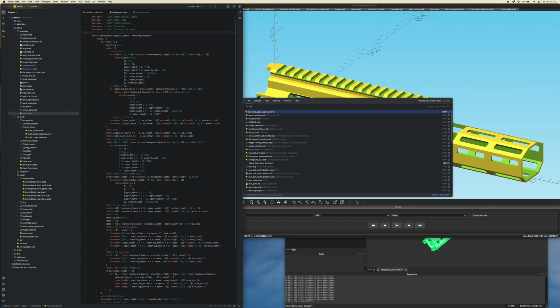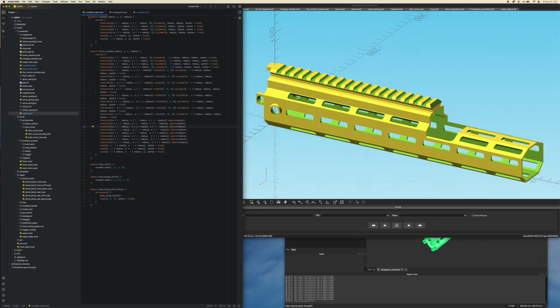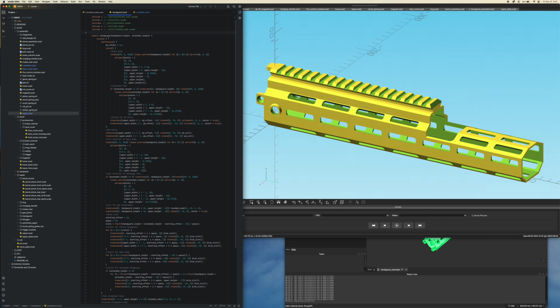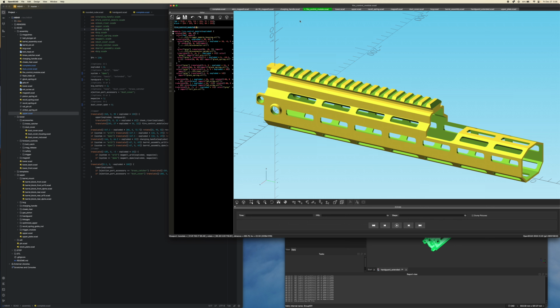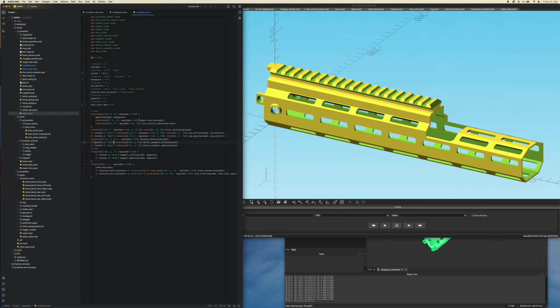So for example, for rounded cube, it basically just takes everything here and pastes it into here. Whereas use only copies in the modules. So for example, it would ignore this and it won't automatically call this function. It will just pull in the module here. So you have to call the module yourself, like I'm doing on line 35, for example.